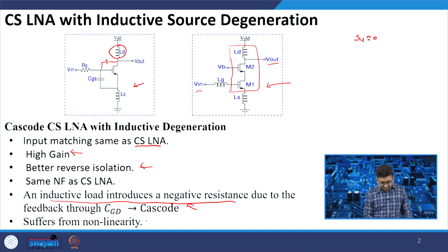But it suffers from nonlinearity, because the headroom required to keep the transistors in saturation reduces, so the overdrive voltage is reduced and that leads to nonlinearity in your circuit. However, it is a widely used LNA because it has all the advantages required in low noise amplifier design.